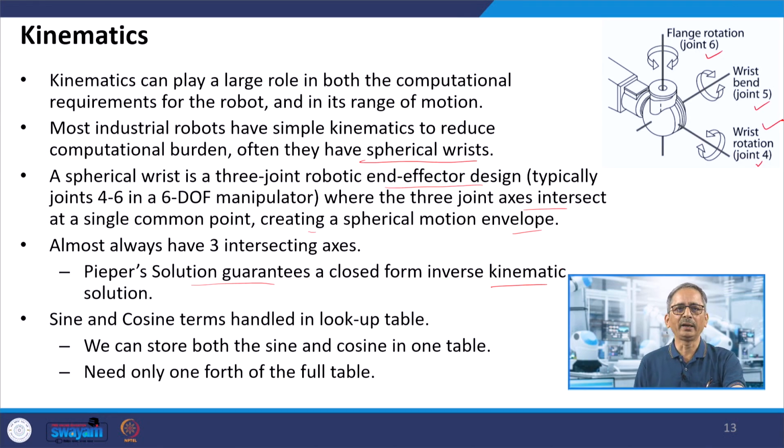Okay. And see, when we are going for these solutions, we will be getting multiple sine and cosine terms, and evaluating these sine and cosine terms is always a challenge. So, usually there is a lookup table. We can store both the sine and cosine values in a lookup table, and need only 1/4 of the full table in order to have all the lookup values.